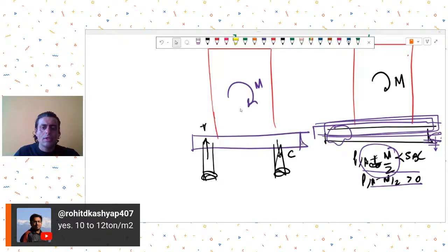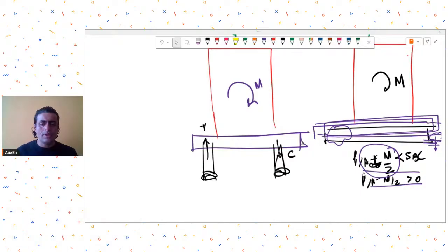So you won't get any good bearing capacities over there. The best option in such cases is to go for piles. Friction piles do work well in your region. So my suggestion is, don't try to go for footings. Pile cap is the best option for you in your region.